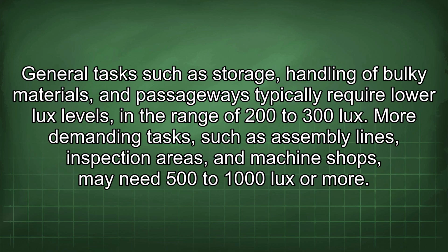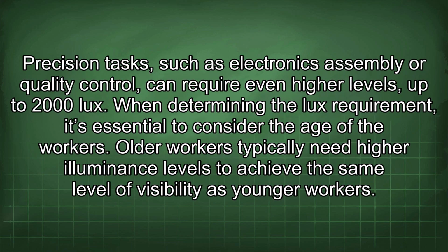General tasks such as storage, handling of bulky materials, and passageways typically require lower lux levels in the range of 200 to 300 lux. More demanding tasks such as assembly lines, inspection areas, and machine shops may need 500 to 1000 lux or more. Precision tasks such as electronics assembly or quality control can require even higher levels, up to 2000 lux.